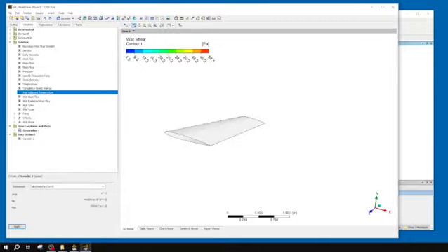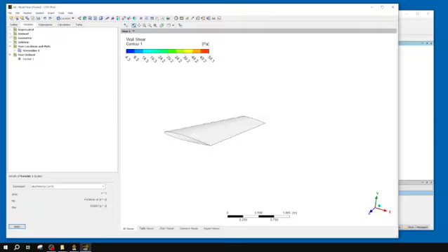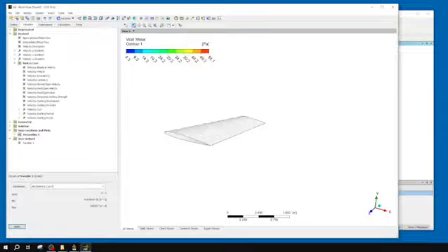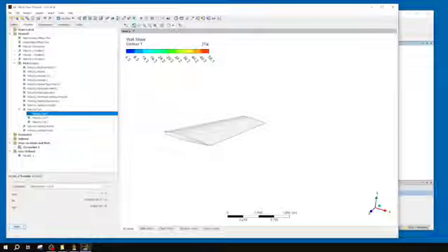So, right, if I wanted to do something with wall adjacent temperature, I'd just write wall adjacent temperature. I got this velocity dot curl x if I go to derived, then vortex core, then into my velocity curl, and here I have velocity.curl.x, and that's the variable I'm messing around with. I'm just using its absolute value. It goes both positive and negative. I just want to take the absolute value as an example for you guys.